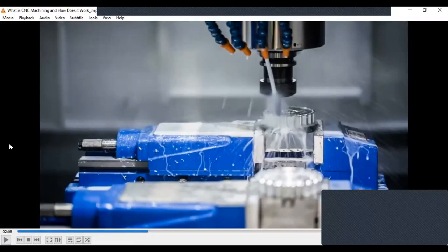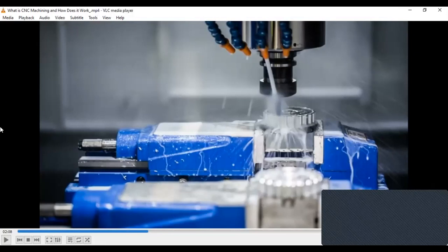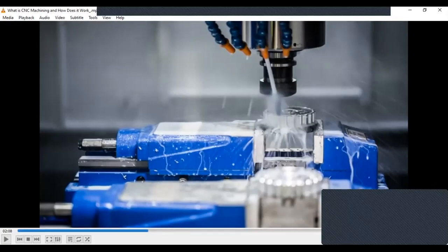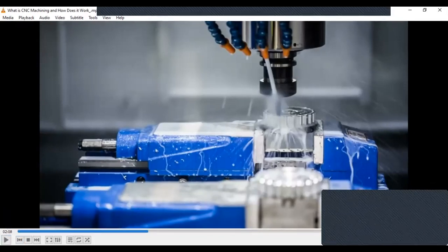Earlier, as he was mentioning, we used to write all those part programs either manually or with punch tapes, right? But now, because you have CAM software, such as Mastercam, which we mentioned as an example, you generate the G codes and M codes. That part program is what is being generated and then fed to the CNC, right? From that, the CNC machine will start executing the instructions.